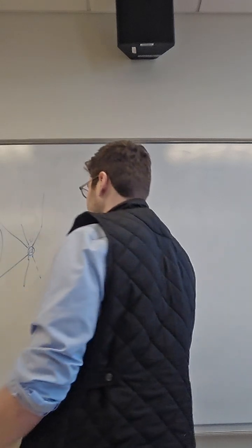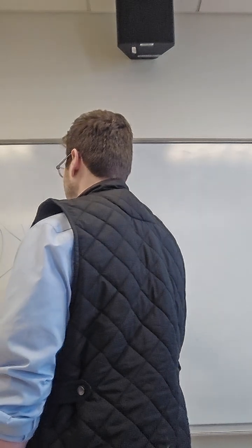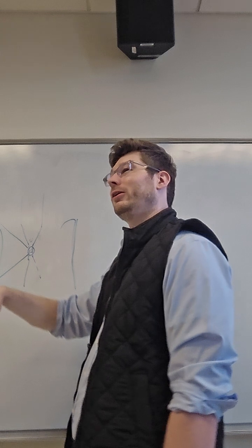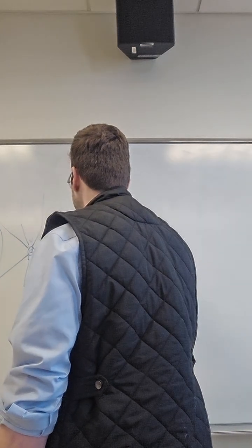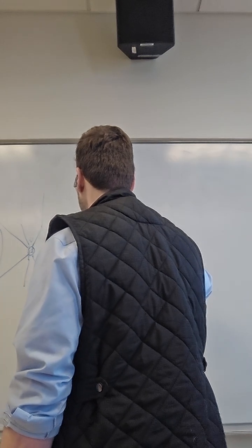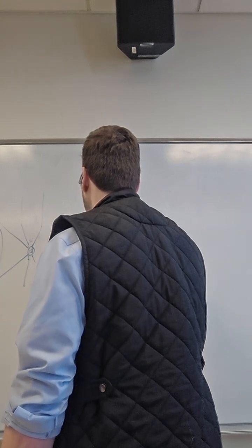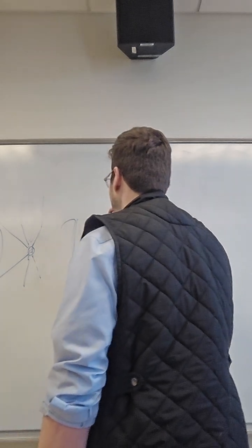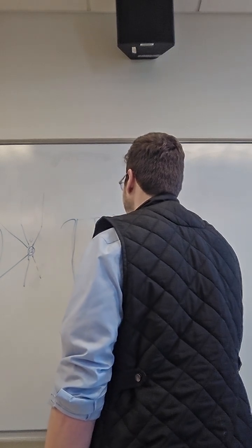Okay, and then it blows up. So if something as small as a micron passes through here, it will make a really big shadow. We'll see the intensity of the light go from really bright to peak down to really dark for a second as the shadow of the speck passes through our detector, and it will keep on going. A larger speck will cast a bigger shadow and get more dark, and a smaller speck won't cast quite as big a shadow. We might only turn a little bit gray as it passes our detector. Okay, so we count the spikes and we can count the number of particles that pass per second.